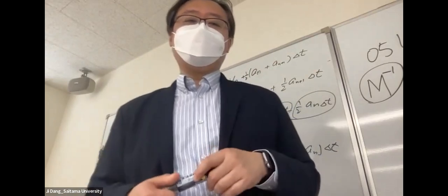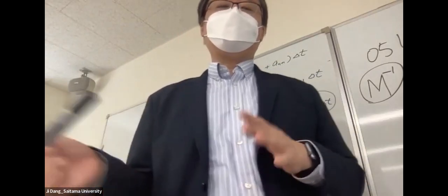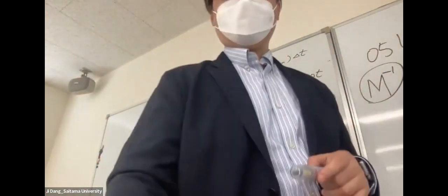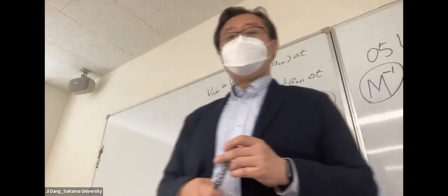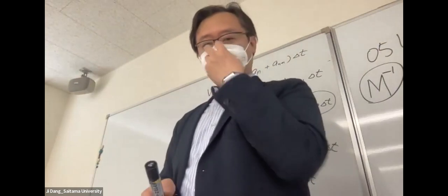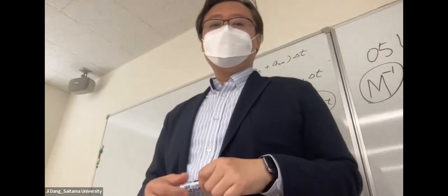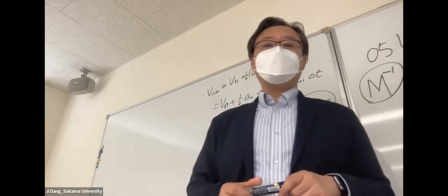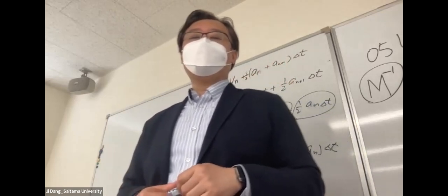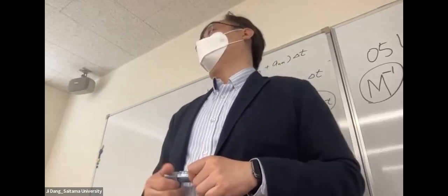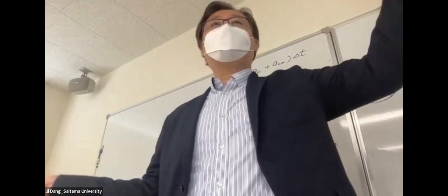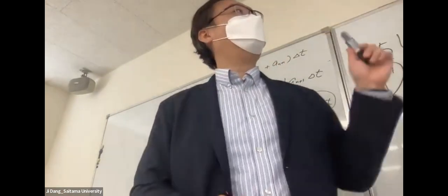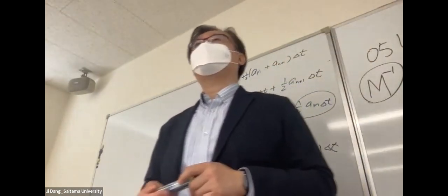Okay, here is what we get. Later we will see we have the incremental method based prediction and then the force based method to correct the result. But we need to learn one more thing about the bilinear model. The bilinear model has a little bit of a feature here, which is that in the beginning, we learn everything based on Hooke's law, right? So the displacement will be proportional to the force. When you have larger displacement, the force increases linearly, which is in the domain of K1, as I showed in this picture.